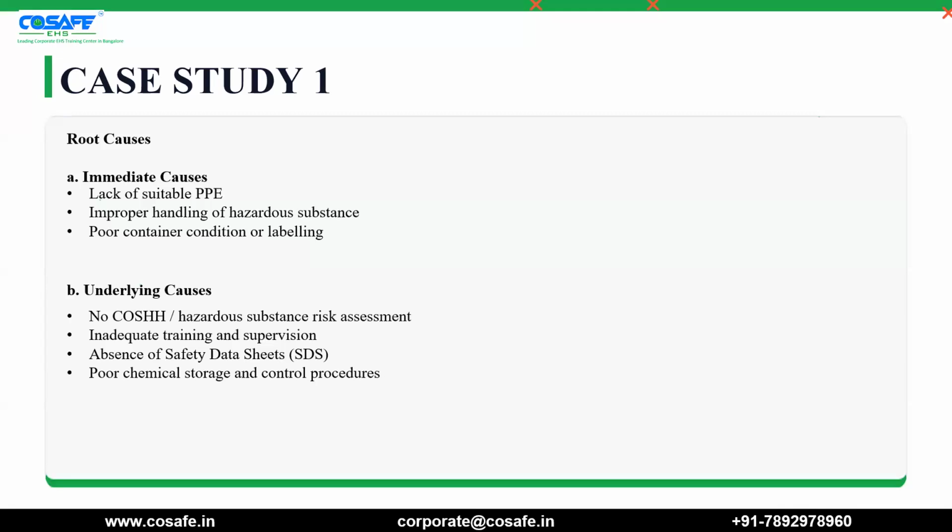No, job safety analysis is different. Job safety analysis is a risk assessment system, a small job-specific assessment system. A safety data sheet is a different thing. SDS gives you the total structure of the component that you are using. It consists of 16 sections. Everyone knows about the 16 section SDS? Earlier it was 8 to 12 sections. Am I right or wrong? Yes, recently it has been updated to 16 detailed sections.